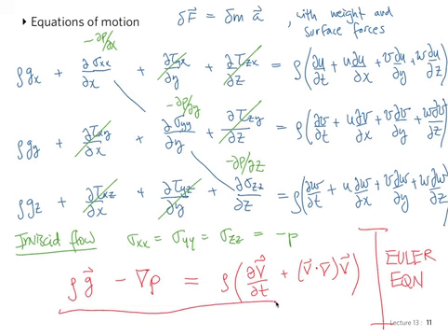And even though this is idealized in the sense that we don't have any shear stresses, and so it's been simplified quite a bit, it turns out that this equation really has no general solution. The reason for this equation to have no general solution is that it is nonlinear. So if you look at this term here, this is the nonlinear term. Why would we call it nonlinear? Because what is our unknown here? The unknown is velocity, of course, velocity, pressure, and density possibly.